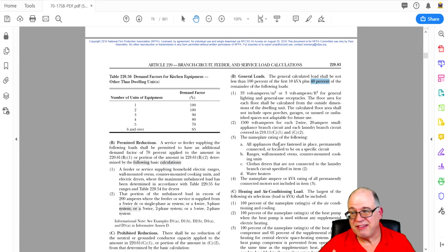Like, for example, if I have a pool house and that load is there during my calculation, it didn't come after, but it's there, and I have that as an appliance and it's a motor, then I'm going to have to consider it. If it's a pool pump motor, it's not considered an appliance, then it might be covered as a permanently connected motor, and then I'm going to have to calculate that kVA into my calculation. Okay, why not? It's there. It's a load. Why wouldn't I consider it? A lot of people go, no, you don't, but they're wrong. I can guarantee you they're wrong.